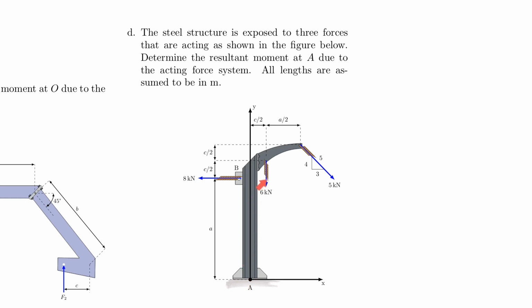So make sure that you break down the forces into proper force components, identify the proper distances, and then multiply it by the directional sense, or add the directional sense correctly, which means positive or negative. Positive for counterclockwise, negative for clockwise. Because it's so much fun, we have one more problem for you on the next page.